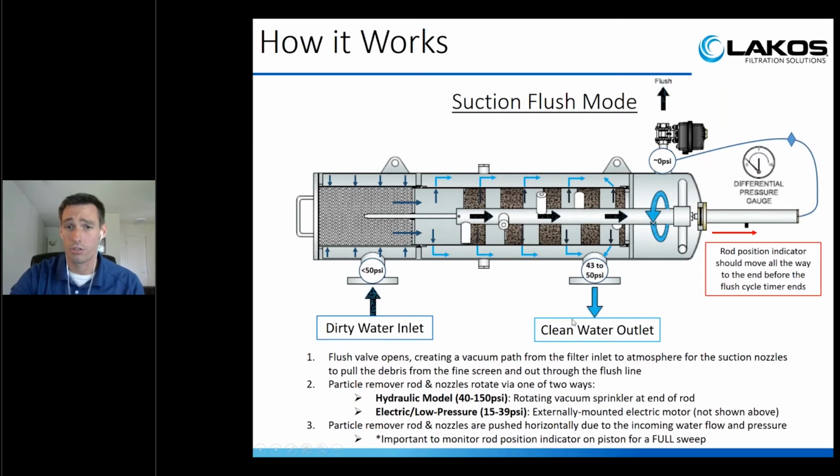The filtering's still happening. You're not cutting off downstream water supply, so you're still going to have water going downstream. Some of the water will be actually going out the flush line. You're basically moving a little bit further out right on your pump curve.